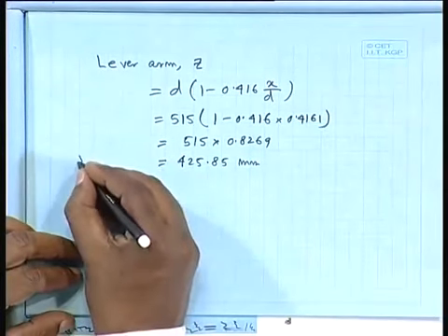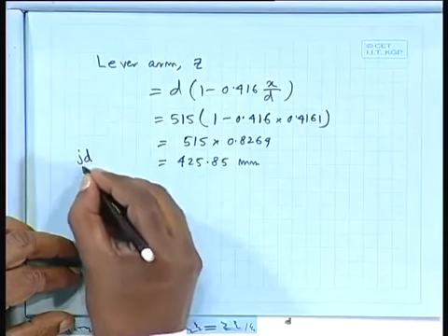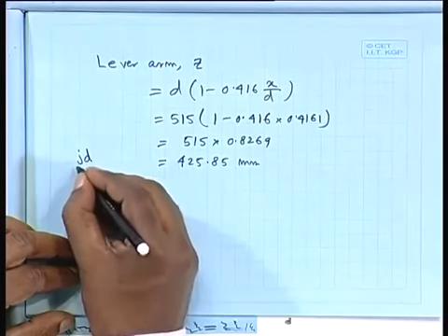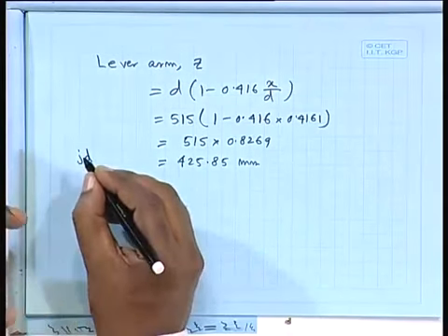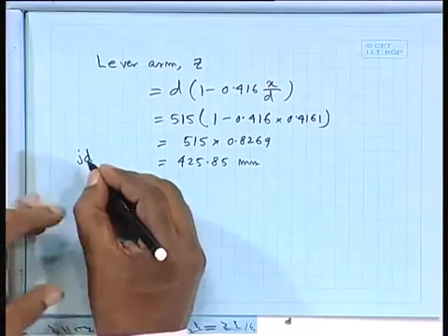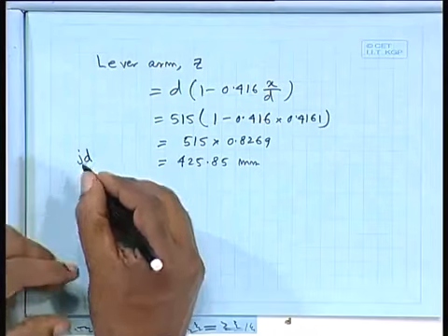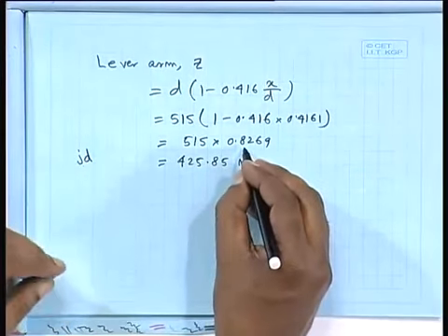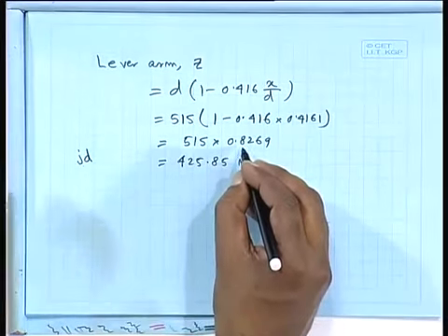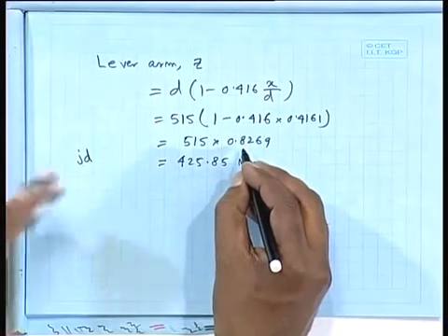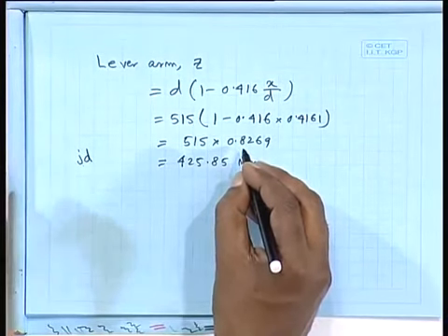If you remember the working stress method, we use some parameters, say jd. d is the effective depth and j is the one from the lever arm. Another one is k. So here you will find out that j could be minimum 0.8 for a balanced section, because it cannot go beyond that.